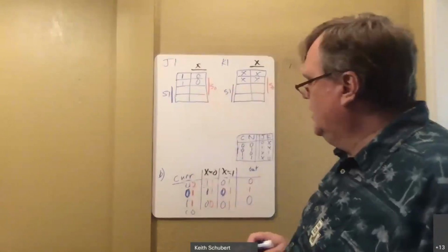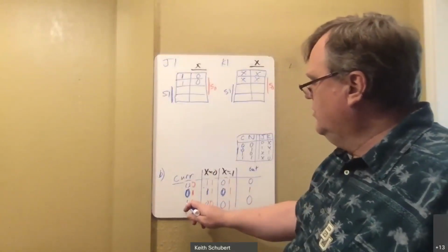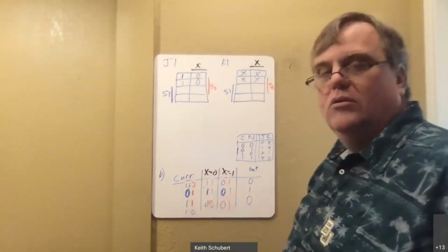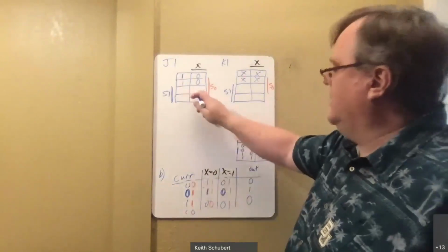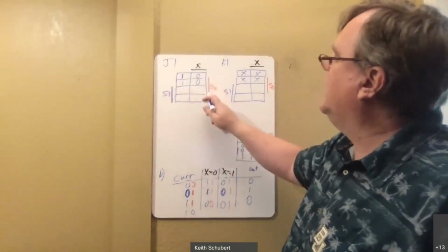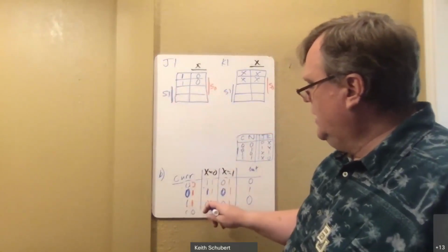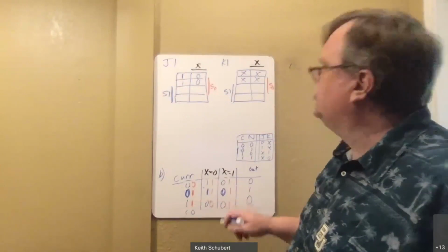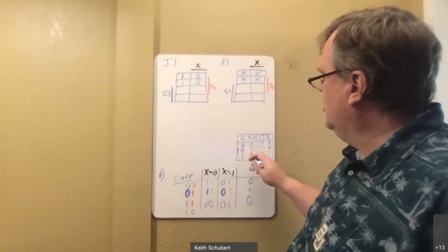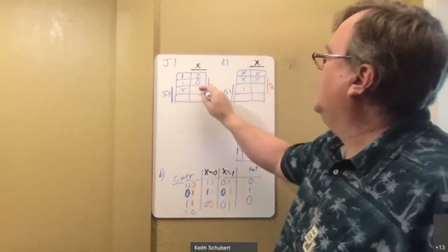Yay. I now go to the lower part of the table. I start at a 1. I go to a 0. And that's actually true for both. Right? So these two lines, when both things are 1s, that's this line. S1 is a 1, S0 is a 1 right here. It starts at a 1 and goes to a 0. So both of these two are going to be identical. Starts at a 1, goes to a 0. That's an X1. And that does the same thing.